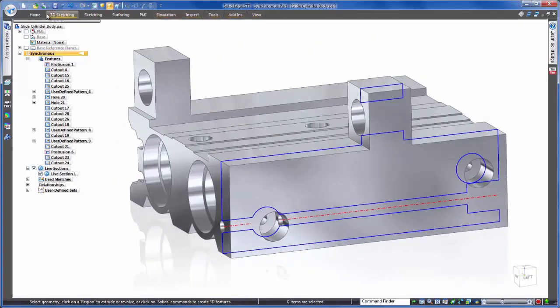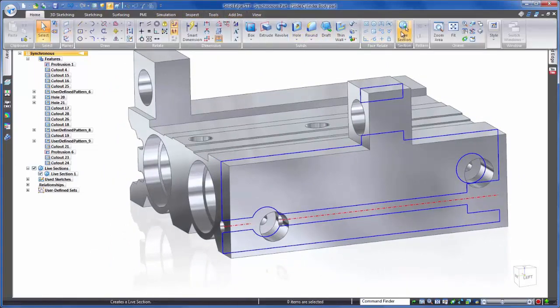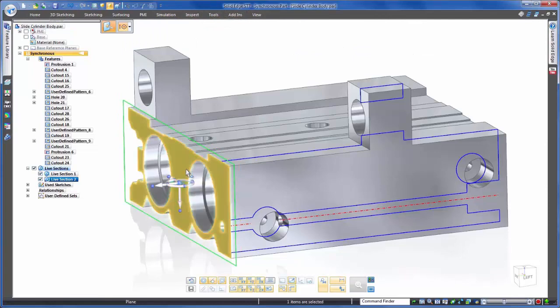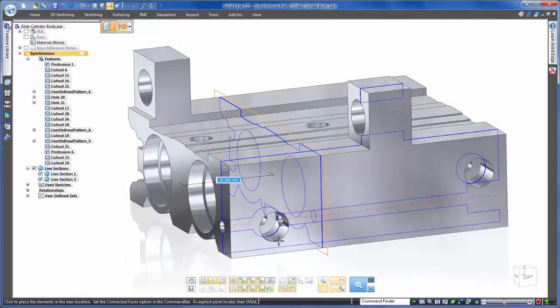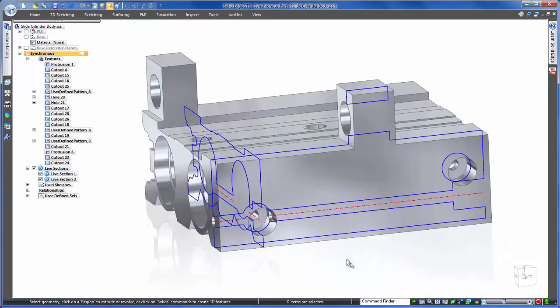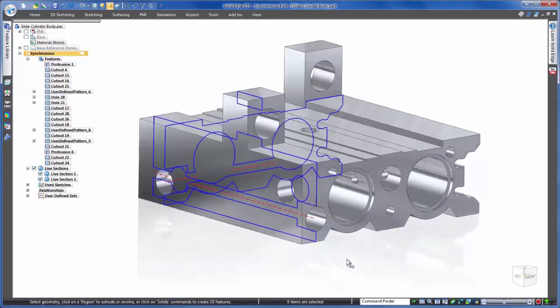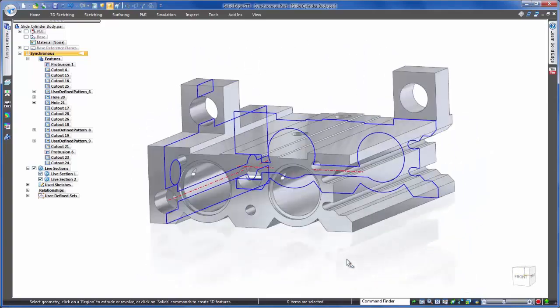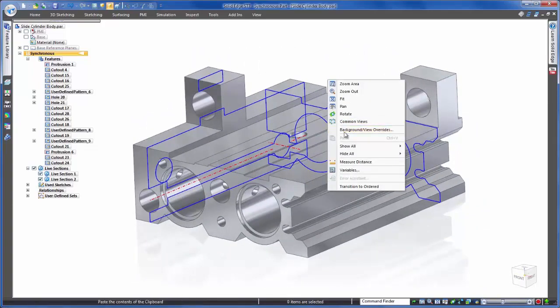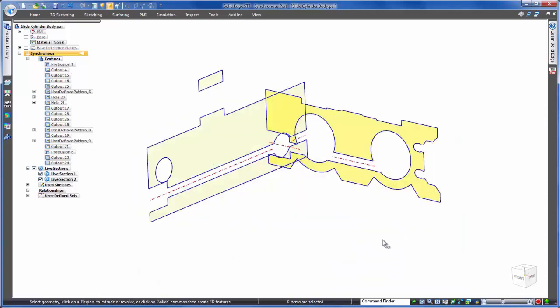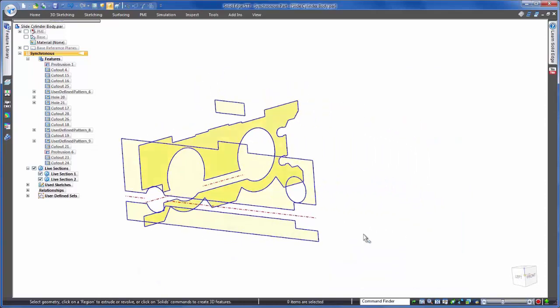Knowing that we need to add clearance between the counterbore holes, but also maintain the design intent further on down the part, we're not going to add just one, but a couple of live sections to the center lines to properly display and represent these features. Quickly turning off our design body, we now have an unobscured view for our required edits.